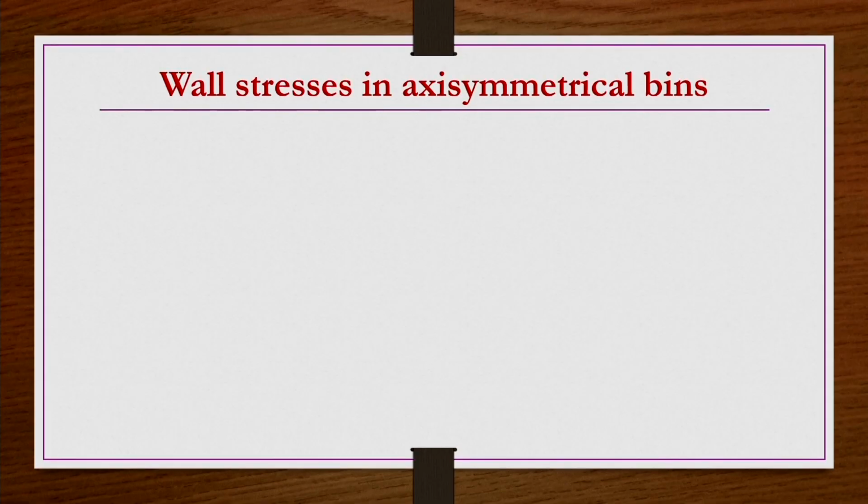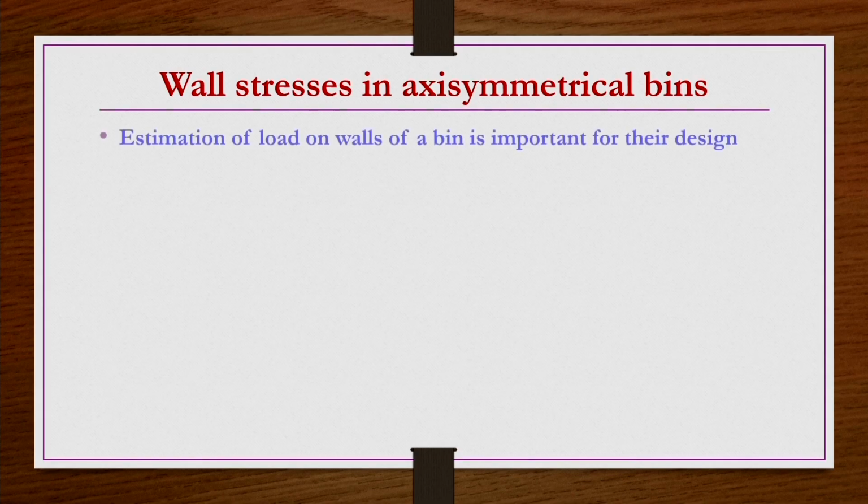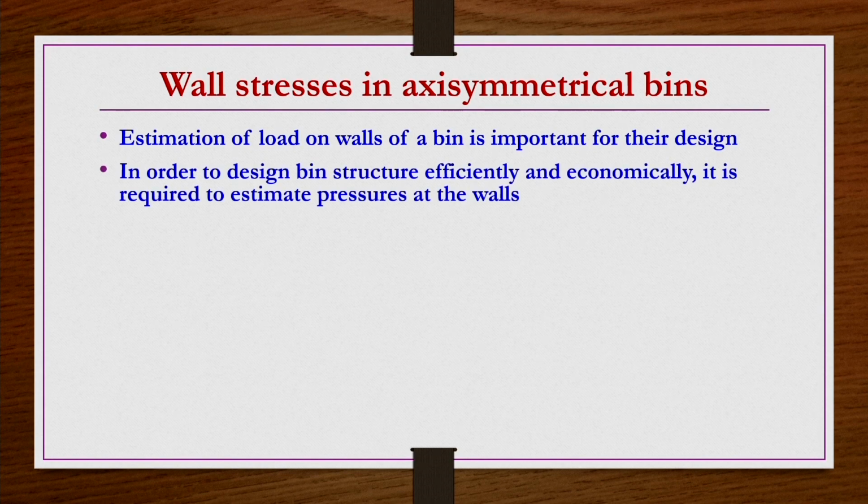Then the most important thing is wall stresses in axisymmetrical bins. We are going to take only axisymmetrical bins. Some discussions we will be doing. Estimation of load on the walls of a bin is important for their design, because in order to design the bin structure efficiently and economically, it is required to estimate the pressure at the walls. So, that is going to decide whether the constructed silo or hopper is of sufficient strength to withstand so much material under static as well as dynamic conditions.